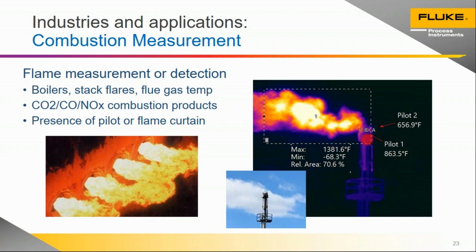And that was these two pilot lights. There's actually 3 in total on here, but we could see 2 of them from the angle that we were at. And we were able to zoom right in onto those spots where the pilots were and make sure that they had an elevated temperature as they should.